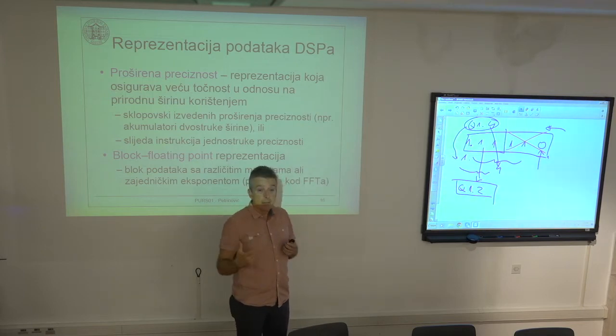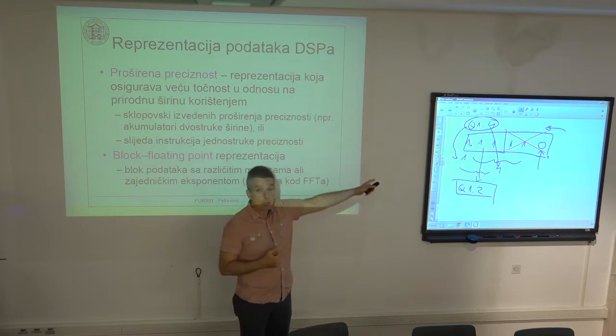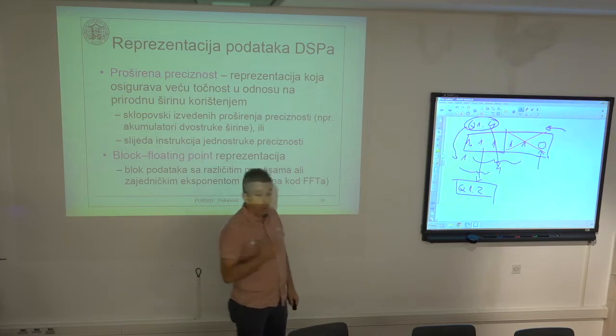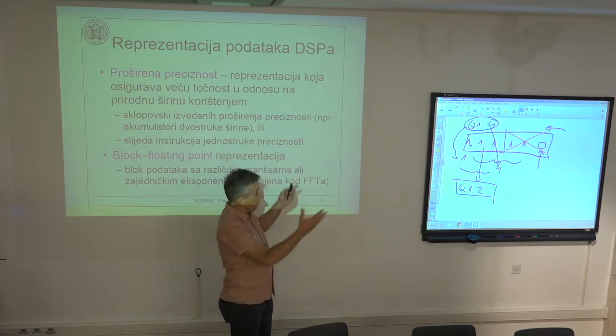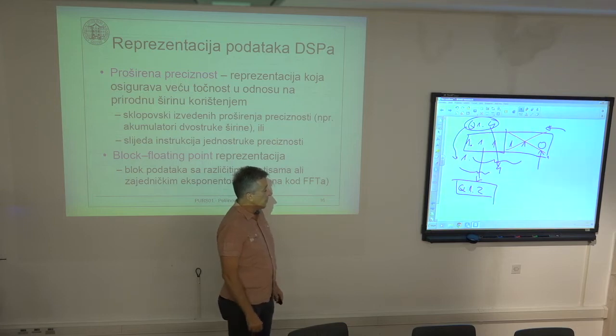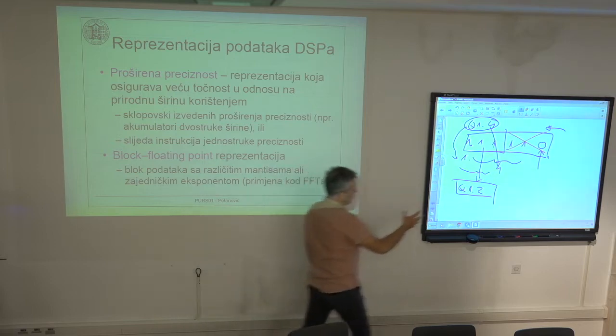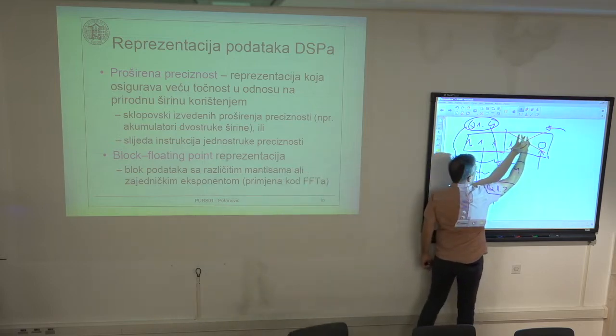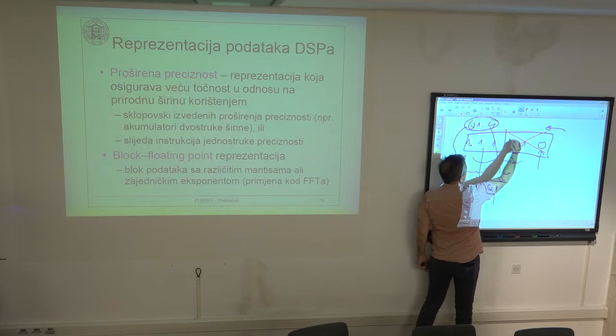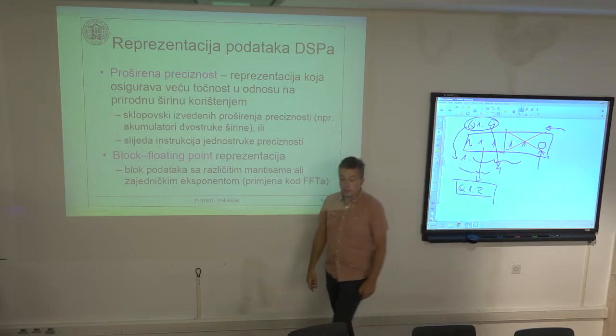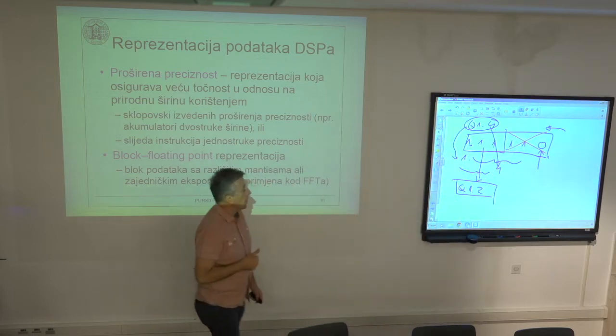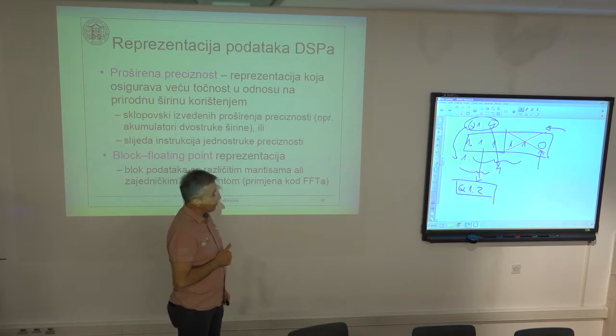And in this case, it would make more sense to take the first larger integer value as a better representation of the product of this double word format. Because in this case, this fractional part, so the representation of the lower word, is larger than 1/2. So it is better to round up the upper word, so to increase the upper word by 1. And this is the rounding operation.